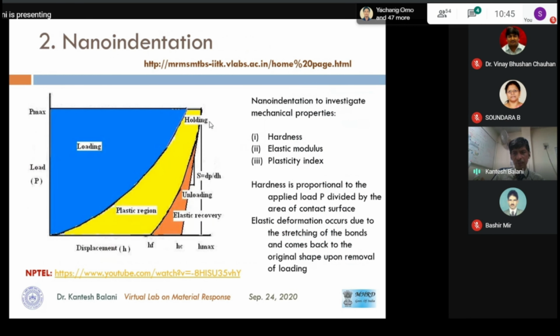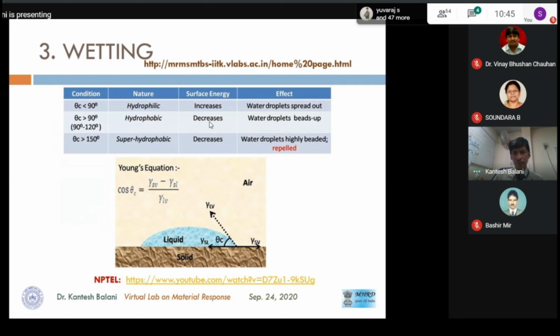Nanoindentation, especially utilized for finding the property of each and every phase. Because once we know that, we can always translate them to a bigger picture. So conventionally, we just take an average property from a region. That can be now split into even smaller domains, and now I can get some more information from them. And typically, they're also utilized in nanoelectronics, where I have very small or thin layers, or when I want to see how the interconnects between say 2 electrodes are working, say in a cell phone. So there I may not have enough material, even for biological structures. So these are also very important in assessing those nanomechanical properties. And again, you have an NPTEL lecture out here.